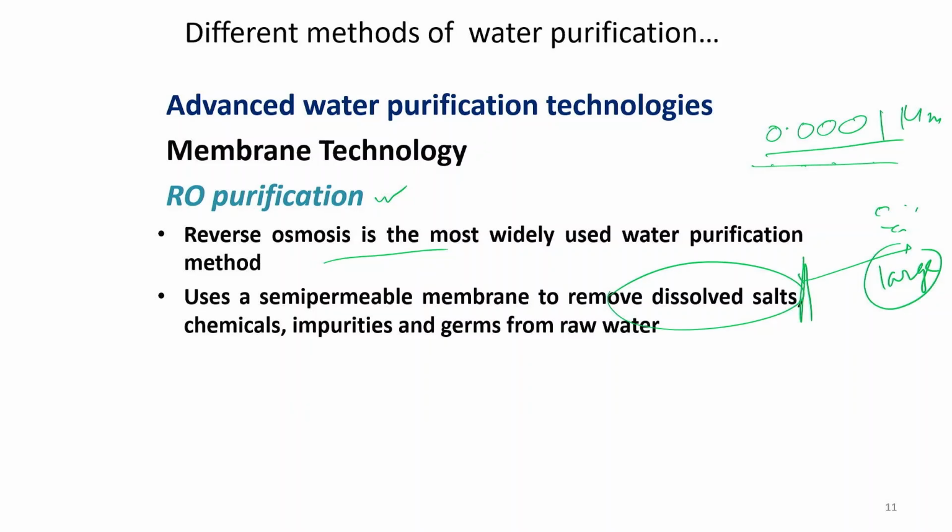Where we need to remove dissolved salt or very fine particles, only then can we go for RO filtration, otherwise the pressure requirement will be very high.